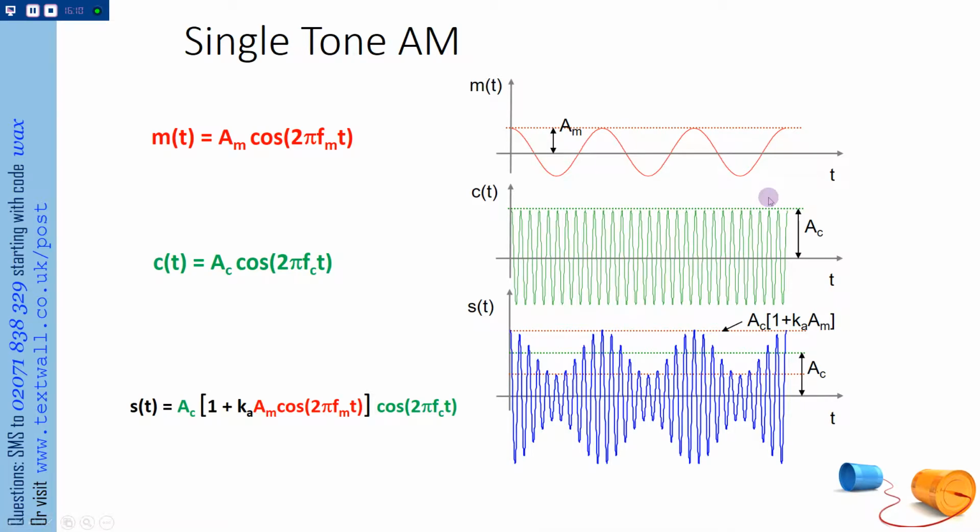So this is what happens mathematically. So this, if you like, is the beginning and the end of today's lecture. If you understand this, there's nothing more to say today. This is what is happening inside the modulator. Everything else we talk about today is just reinforcing this. So what have we got here? We've got the red signal, low frequency, baseband signal. Remember we said AM cosine omega mt? Now I've simply written it as 2 pi fmt, same. And the carrier AC cosine omega ct, I've simply written it as 2 pi fct, same thing.